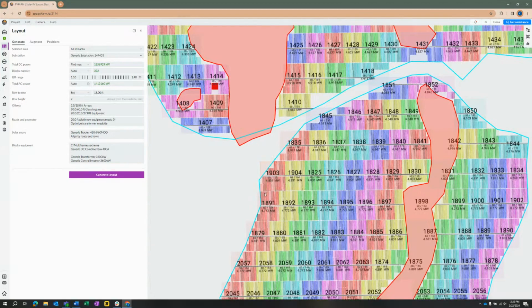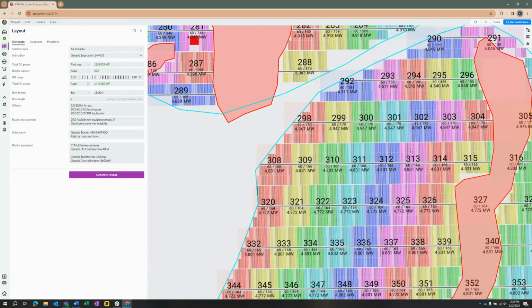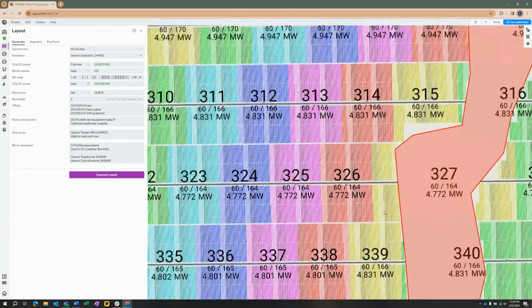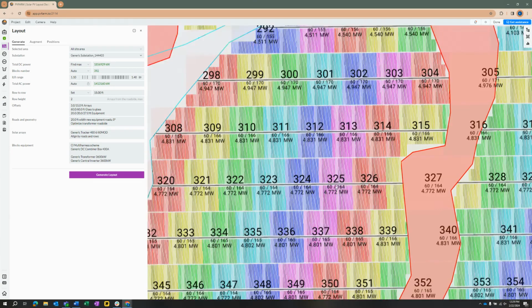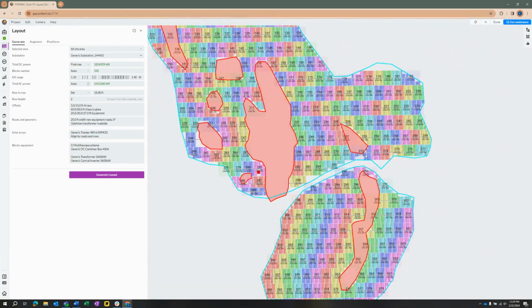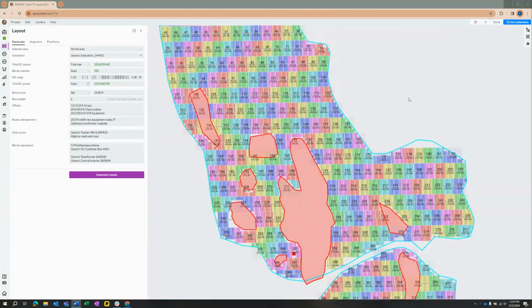Okay, and this is finished running, and you can see we don't have as many outliers. Our blocks are much more aligned now. It's much more of a constructible product. We do still have 1.85 gigawatts. It did go down maybe a couple hundred kW, but really not that much when you compare it to having a more constructible site. Now, that was just using the generic tracker, and what we want is to find the specific tracker type and length that's going to work best for our site.